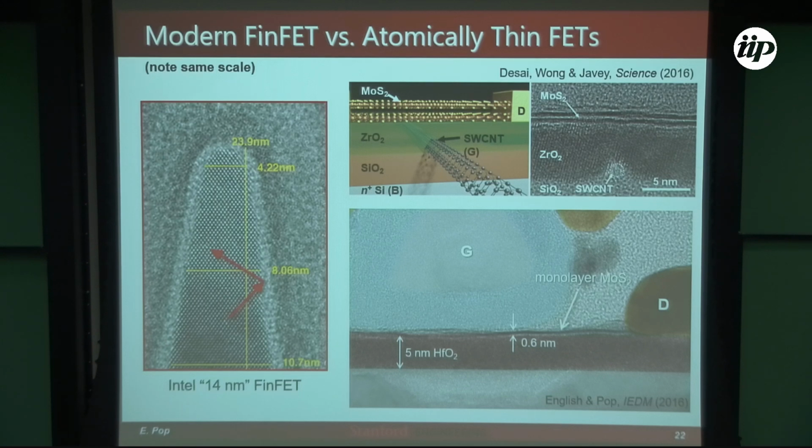I want to emphasize that again, that what's killing this is not just our ability to make things smaller, but the fact that electrically this will actually get worse as you make it smaller. Variability on one hand, and then the mobility gets worse because, as I showed here, this is obviously my cartoonish way of drawing, electrons will scatter from these otherwise imperfect interfaces, right? So there are obviously silly academics like Ali Javey's group at Berkeley and others who are trying to see what we can do with the atomically thin materials, right?